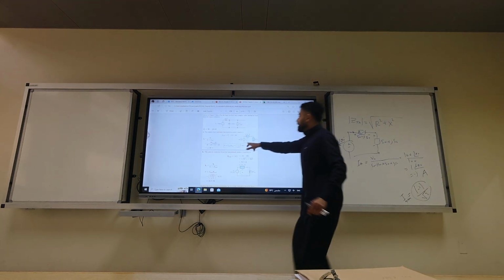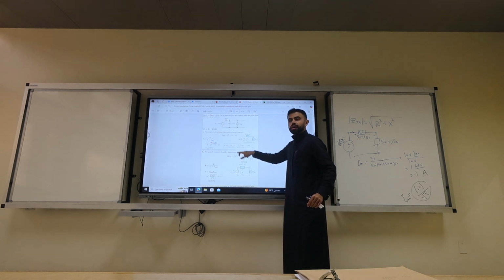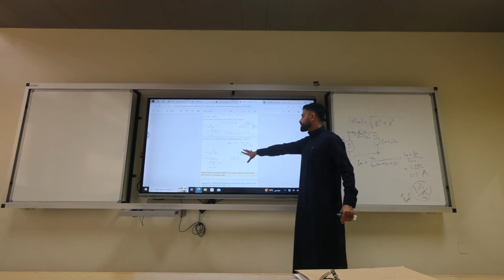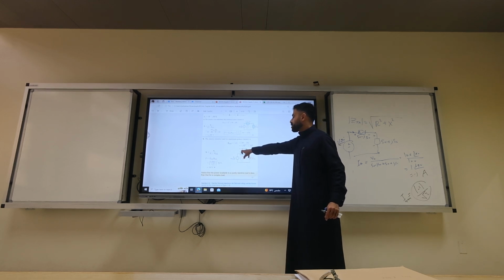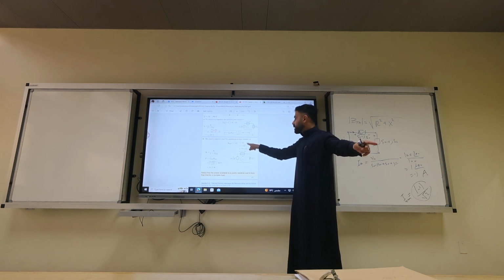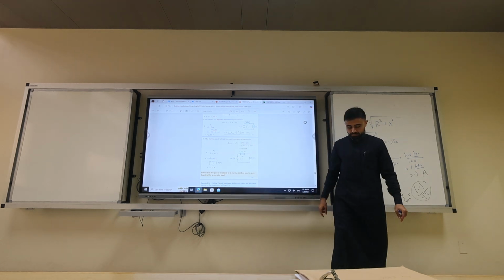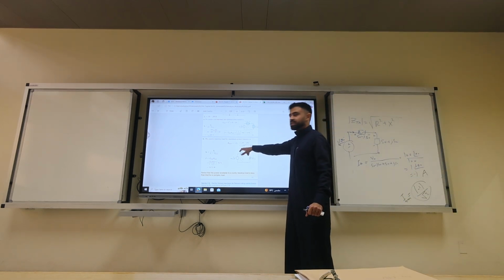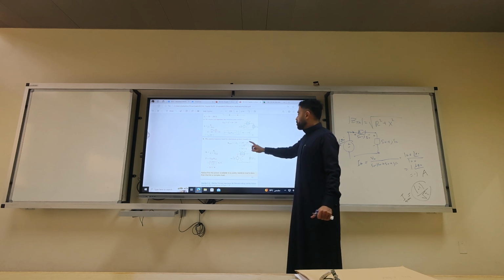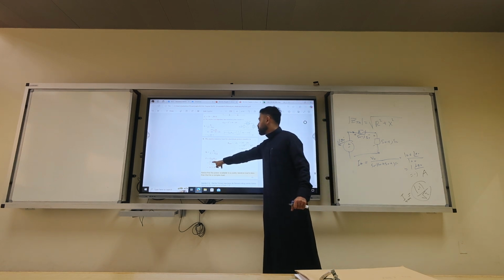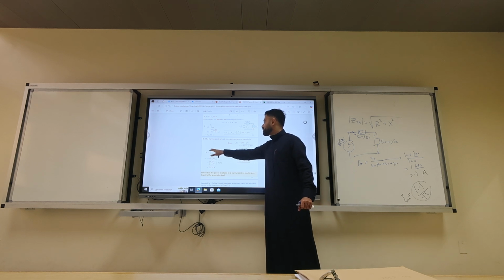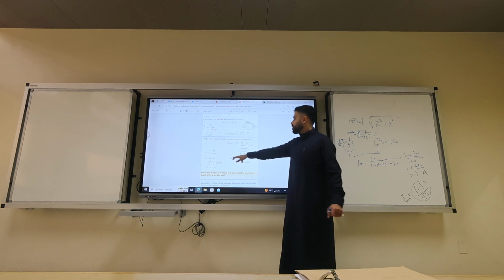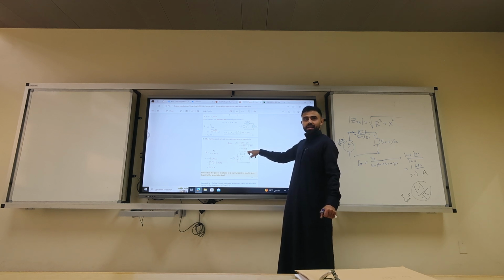You see it's 50 times 1 over the square root of 2, all squared. And you get 25 watts. But if it was purely resistive, we are allowed to connect the square root of 50 squared plus 50 squared. What's the answer? Well, I can see it here. It's 70.7 ohm. So I can calculate the current. If we calculate the current, it will be what? V Thévenin over 50 minus j50 plus 70.7.